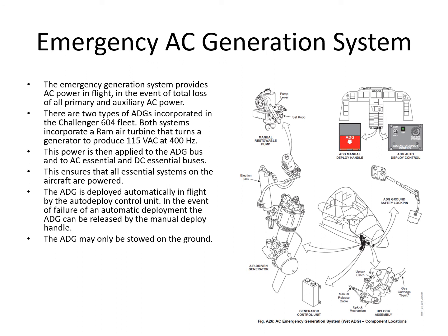The wet ADG uses a squib, like a fire bottle squib, to release the lock, and then the ADG deploys. The dry ADG uses a solenoid operated lock release. The locking mechanism itself is very similar, it's just the release mechanism.